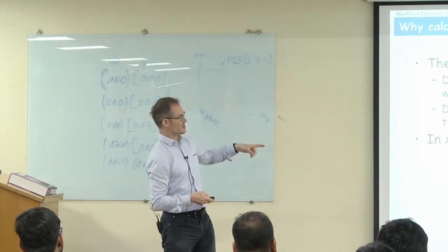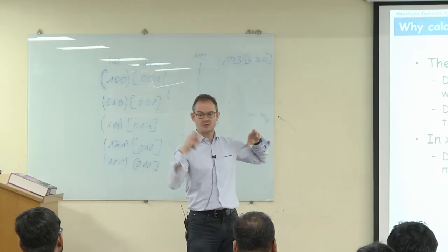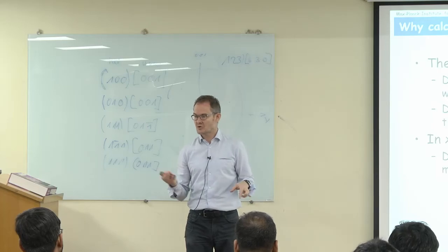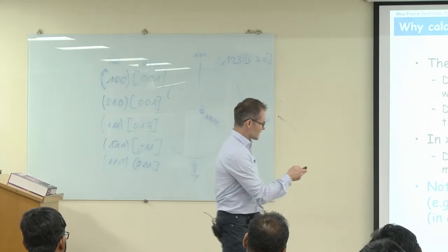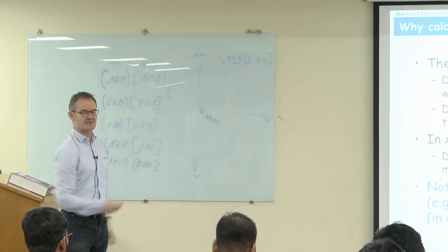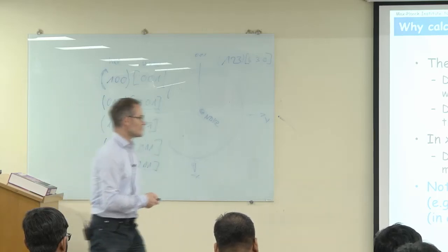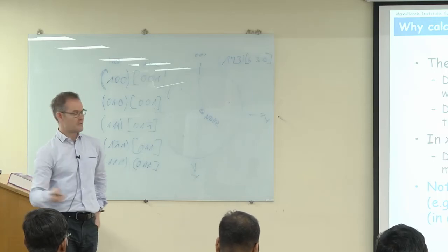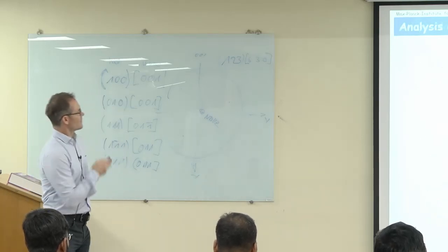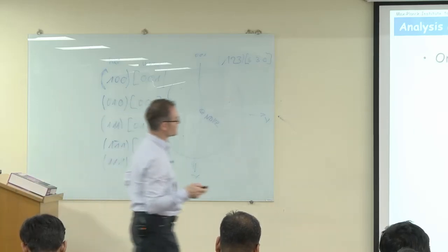So in X-ray texture measurement, you actually need to calculate the ODF from the pole figures to understand which kind of orientations are behind that. Good, but we're not doing that. EBSD is in this regard a much more straightforward and much more powerful technique. We're doing individual orientation measurements and not pole measurements. And now we're coming quickly to the orientation measurements.